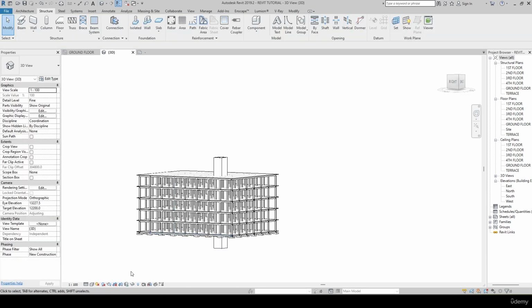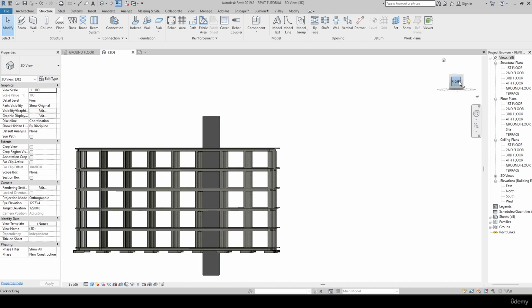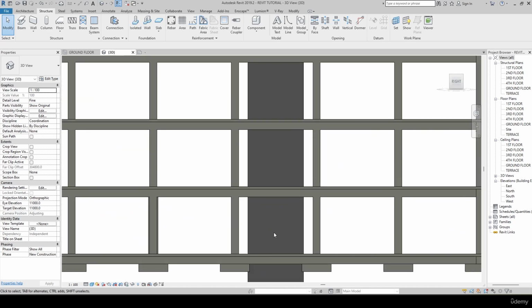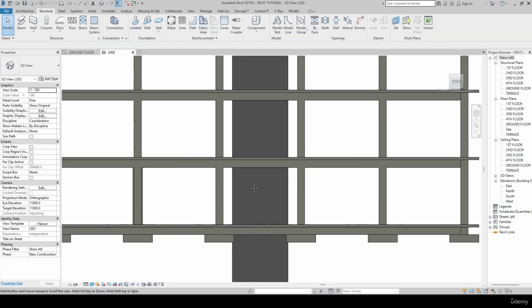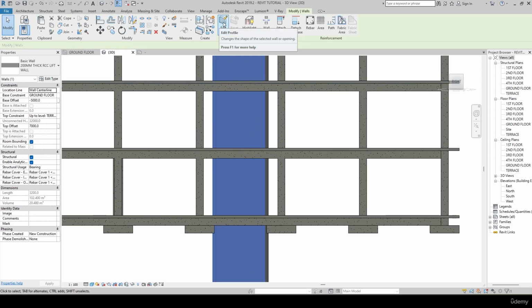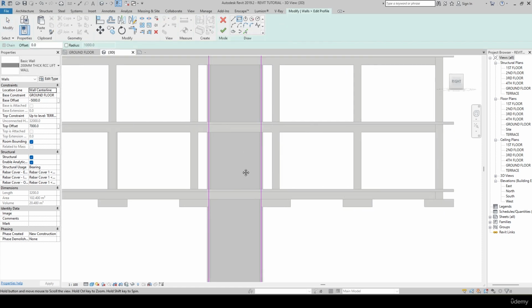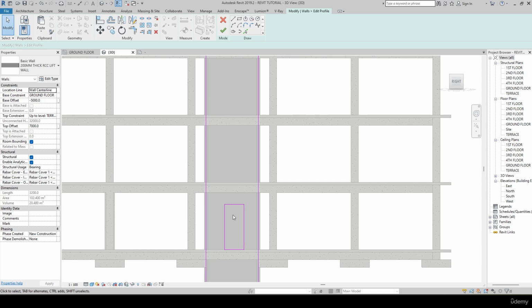Okay, now go here, consistency color, I'll go to this right view. I'll add the lift openings here. So in order to add the lift openings, I'll go to this, or maybe the front panel. Okay, I go to edit in plane. I'll go to here, I'll make the openings. Okay, so I'll keep this as 1200 by 2700. It's the same.